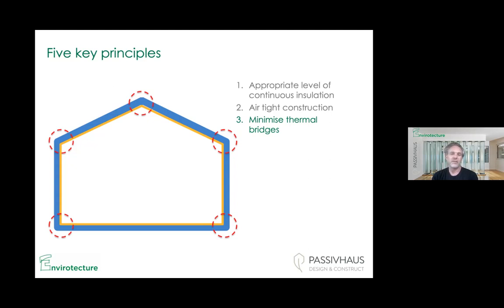Obviously, then it depends where that water ends up. And I suspect there's probably nobody here this evening who has not seen that happen at a house in Sydney. It's incredibly common. So minimizing thermal bridges is partly about comfort, partly about health, and partly about not damaging your building, because it's fairly annoying to spend $1 million or whatever you might spend on a house and then have the whole thing start to rot and fall apart.